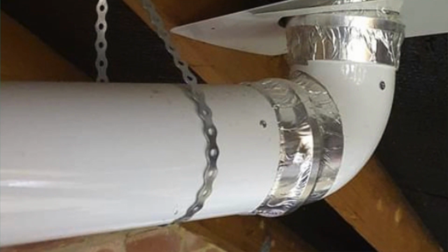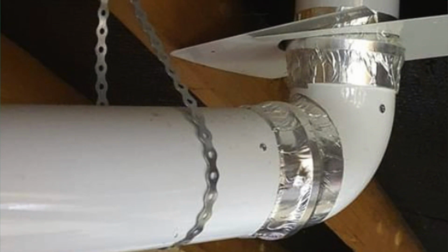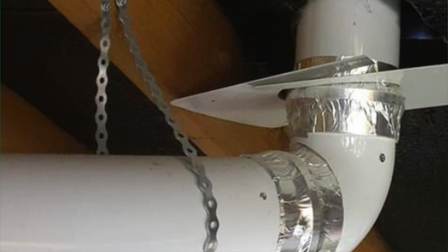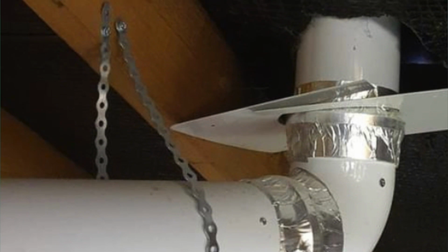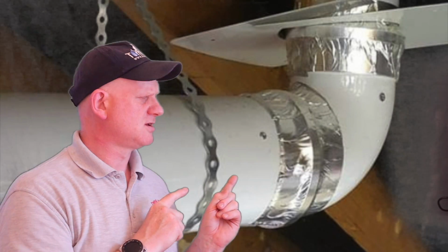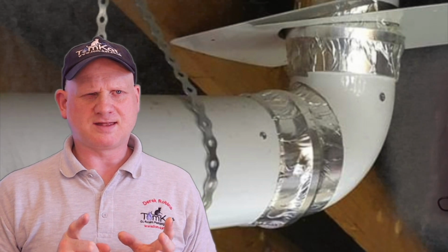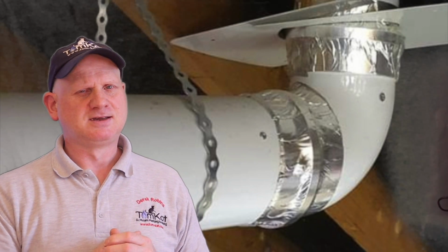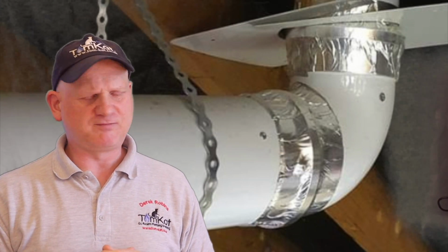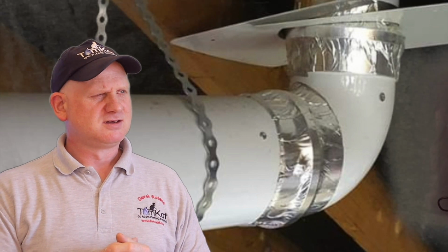Now again, if you're out to do a landlord's report and you notice the flue goes vertically into the loft and then through the roof, we must get into the loft and inspect it. And this is what you find when you get into the loft. As you can see from the picture, the flue is inadequately supported because they've used this banding, and they've put some tape around the actual joints. So bear in mind those 2 scenarios. What would you classify this as?